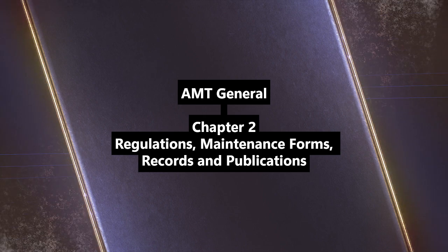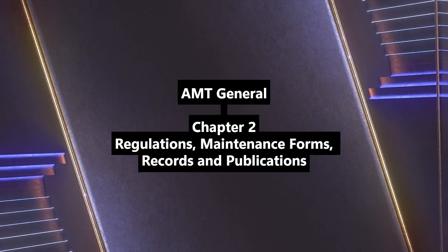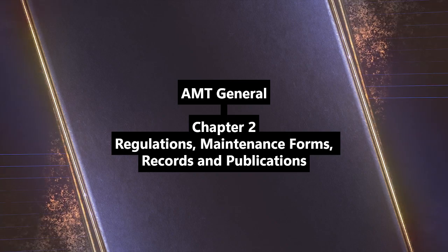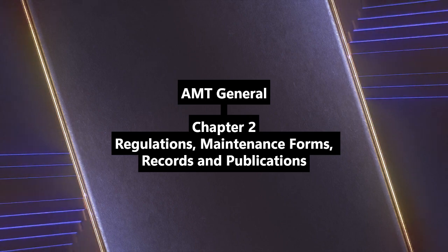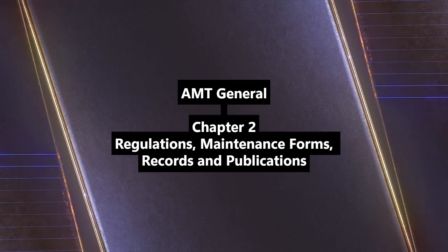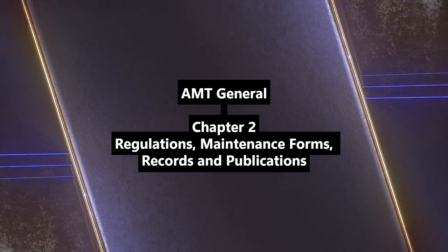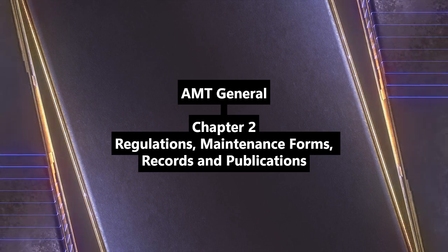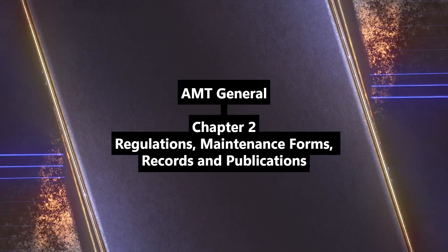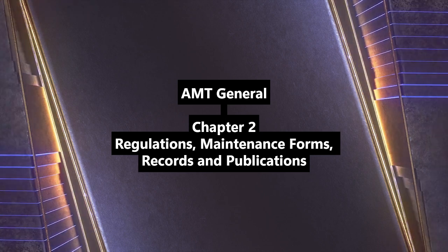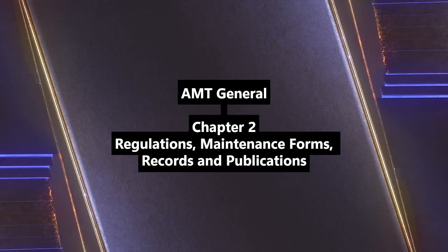Okay. Sections 91.411 and 91.413, the 411 and 413 tests again. It just reinforces the 24-month requirement and links back to Part 43 Appendices E and F for the procedures and who can perform them. Section 91.415, changes to inspection programs. Can the FAA make you change your program? Yes, if they deem it necessary for safety; the owner gets 30 days to contest it. Section 91.417, maintenance records. You said this was fundamental. Absolutely. It lays out what needs to be kept. 4 types of records are mentioned.